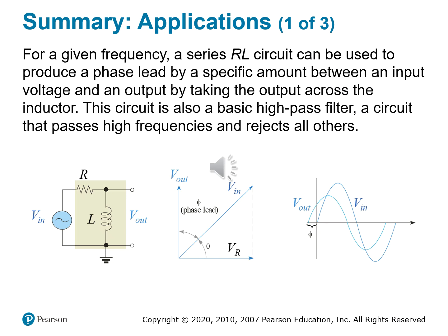By measuring the voltage across the inductor, you're observing the leading component of the series voltage drop. As frequency increases, V sub L becomes more dominant, because V sub L is equal to 2 times pi times frequency times inductance. Remember that there's a direct relationship there, so that increases with frequency. This results in V sub out leading V sub in with a phase angle that grows with frequency.